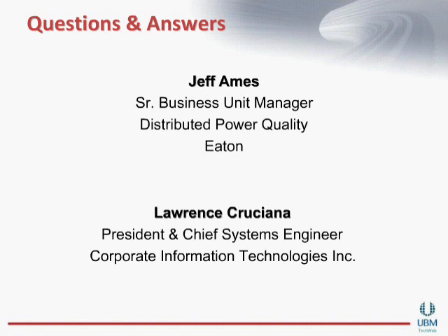Almost all of those power distribution hardware devices have strip level monitoring. Some of them have group level monitoring, and others even have outlet level monitoring of the actual power being consumed at the receptacle, if you will. Higher levels of aggregation are available if you go further and further upstream in an electrical sense, upstream from that final point of electrical consumption.